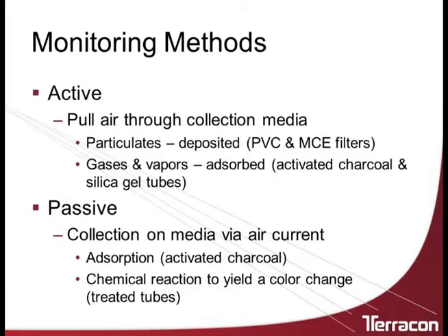In the passive approach, the collection on the media takes place via air currents. So you basically wear a badge, and the air current with the contaminant gets deposited on the media, either through adsorption. Again, they would use an activated charcoal media, or it would be a chemical reaction. So you'd have an inert type of material, the manufacturer puts a chemical on there, and it would react with that contaminant to form a color change.